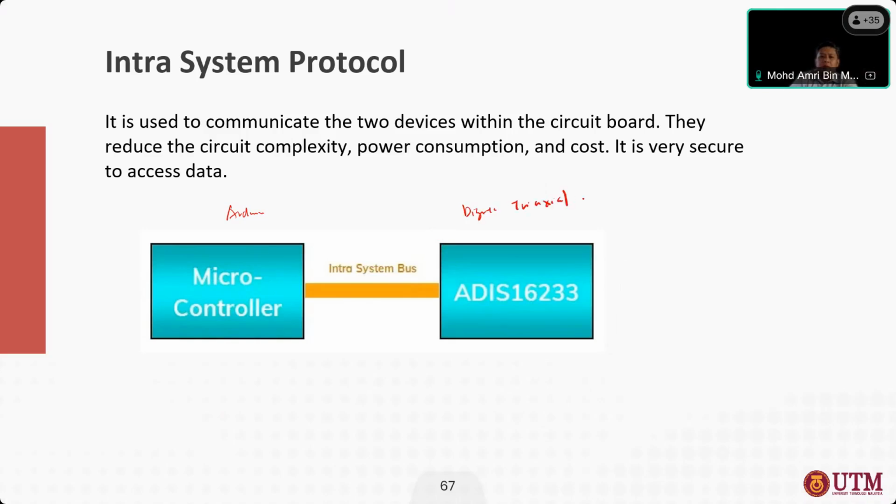three-axial vibration sensor. But if you remember, we can also communicate with our Arduino using an LDR module, and our LDR module has digital and also analog output. You can communicate with the microcontroller with digital and analog, but analog is more for connecting to the ADC, while for digital, the data is converted into a digital signal and transferred into the microcontroller.